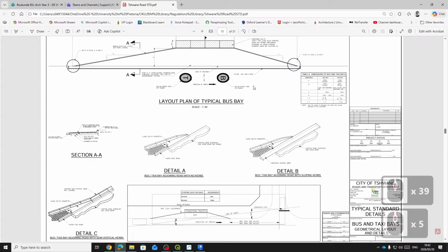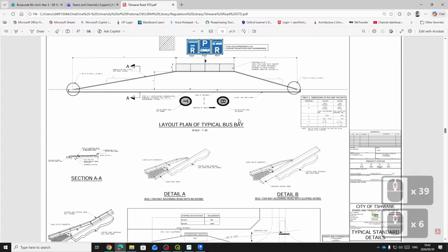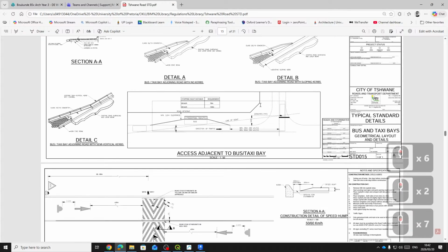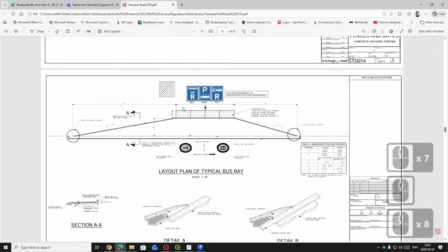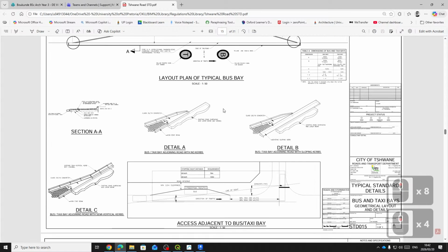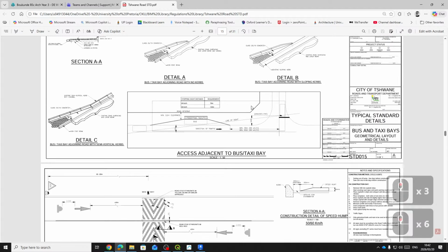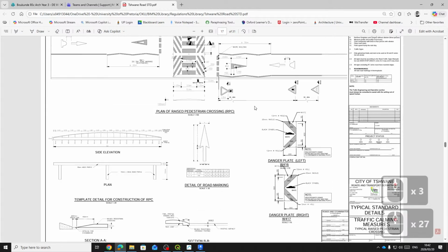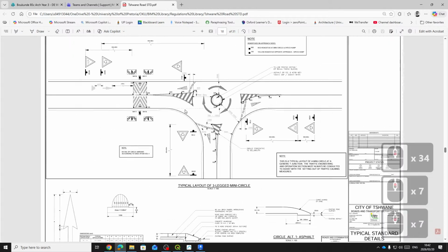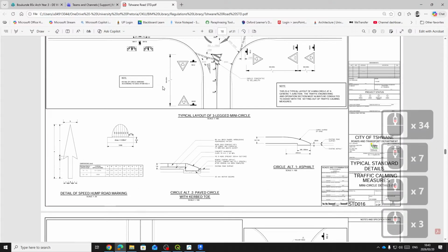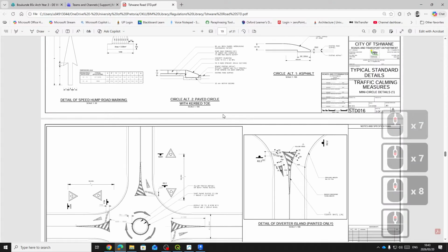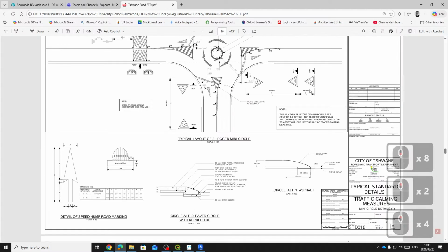So if you're going to provide a taxi drop-off area or bus drop-off areas, this is how you don't waste your time. The details here are what you must do in order to cater for a taxi bay or a bus. So if you've got any of those services around your site, you need to document them, or if you need to provide a service like this, you'll need to detail it as follows. Okay, so just go and have a look at this information. Maybe a pedestrian crossing to access your site. You can instate those. Okay, so consider this information, the detail of mountable curbs.